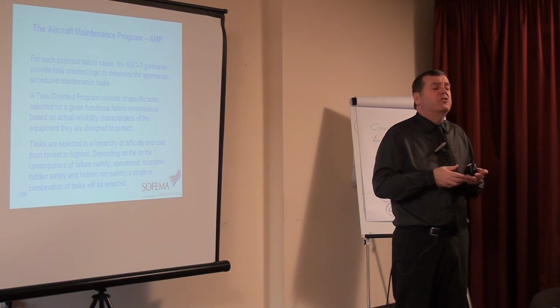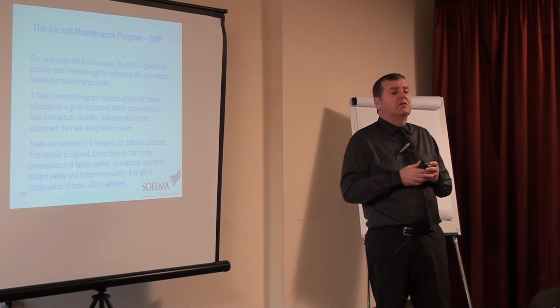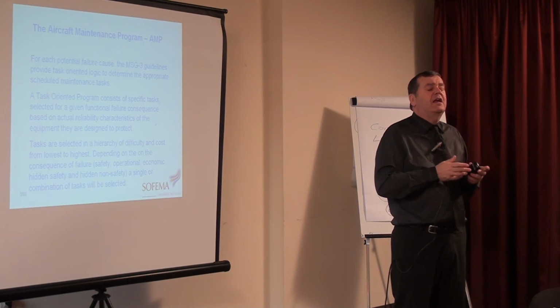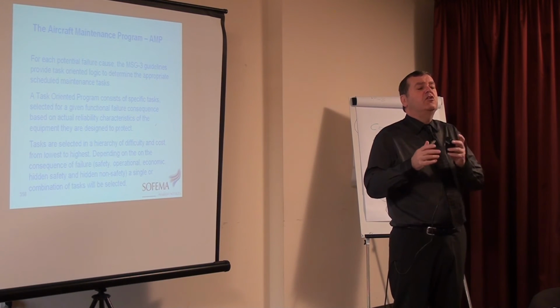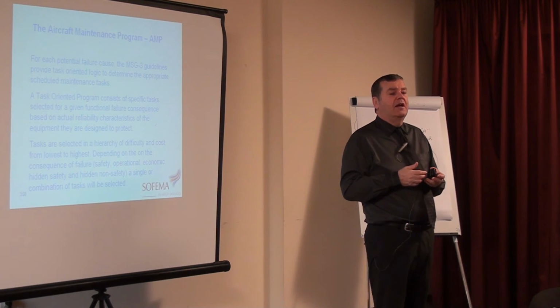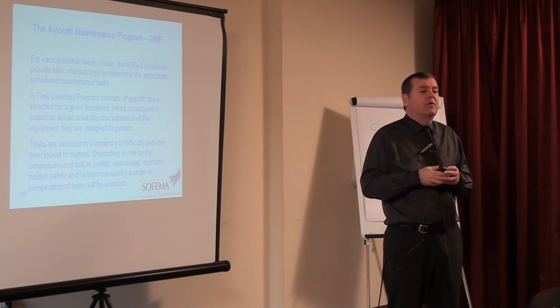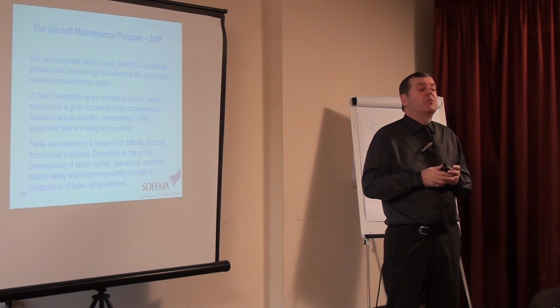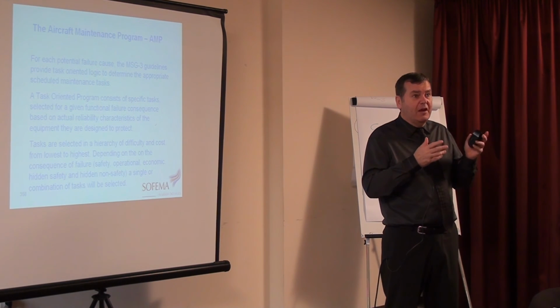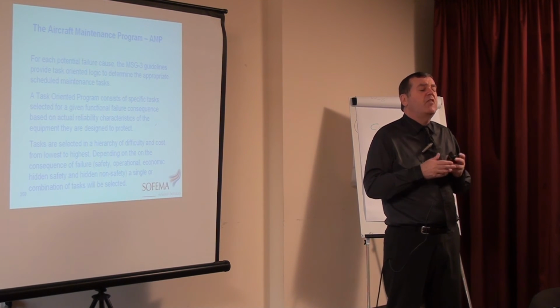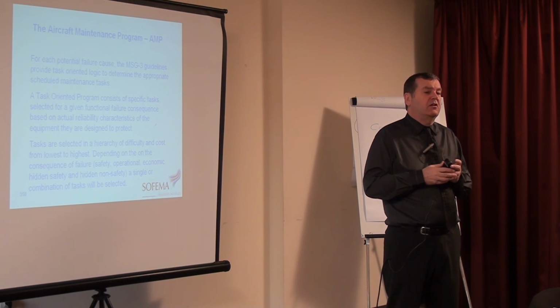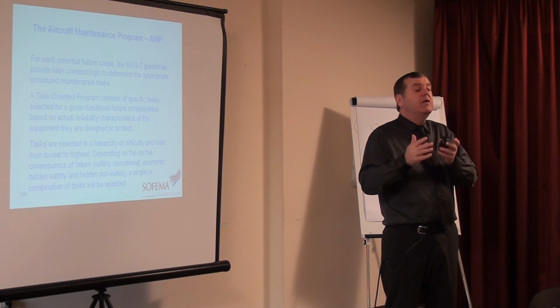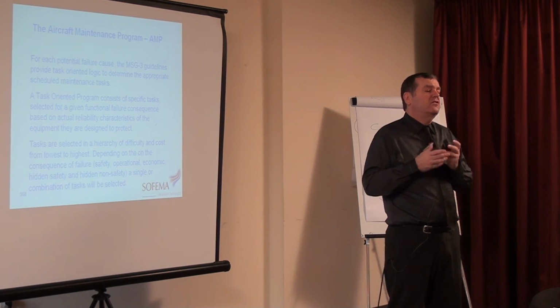And this process has been developed over decades, understanding how to build in safety and redundancy. And as a byproduct, it allows us to develop a minimum equipment list and say, okay, for 3 days, it's acceptable that this hydraulic pump is not working, for example. And that gives us the flexibility to keep the aircraft in service without impacting the safety. Why? Because we've built in a margin of safety. So we're not impacting safety, we're impacting our margin of additional safety. This is the rationale.